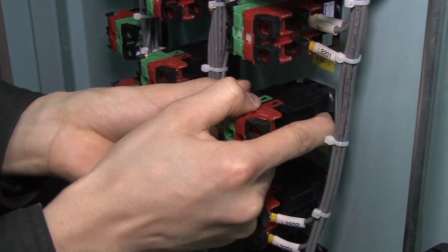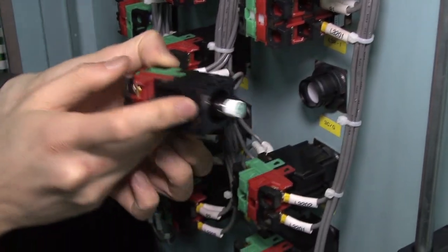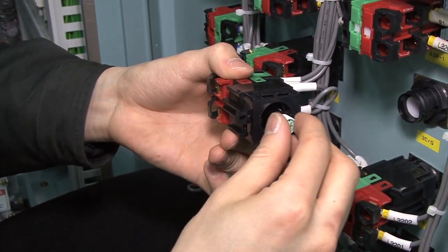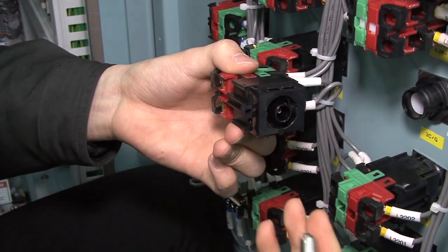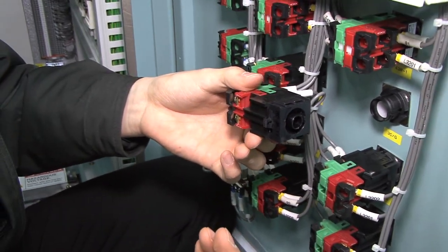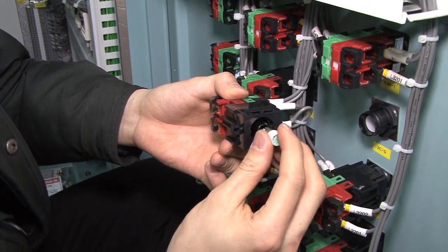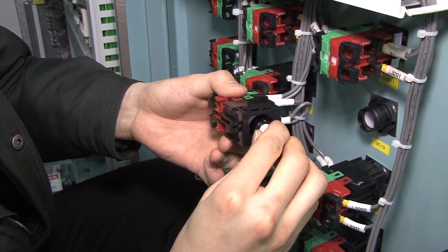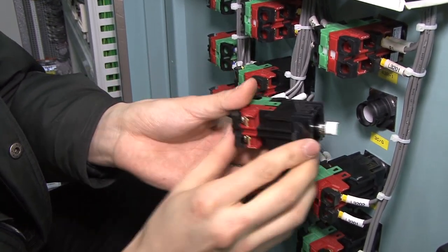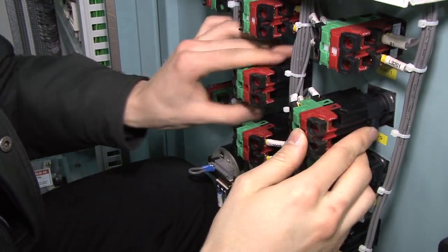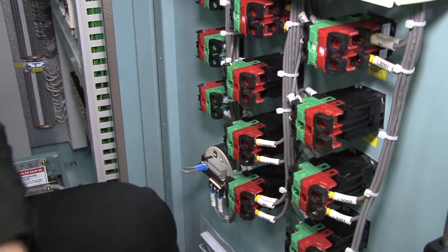Lamp bulb. Applicable equipment and location: PDE. Step 1. Take apart the power part of the button lamp. Step 2. Remove the defective lamp by turning 90 degrees to the left while pressing inward. Step 3. Check color and voltages of a new lamp and replace it, following instructions in reverse order from Step 2 to Step 1.